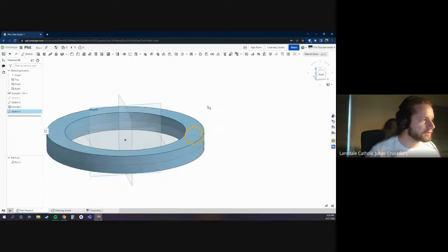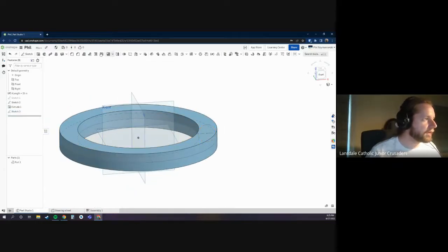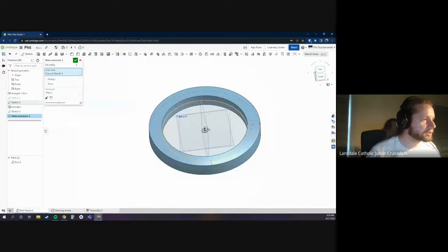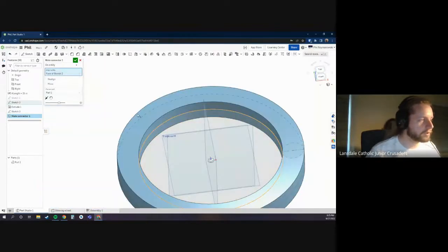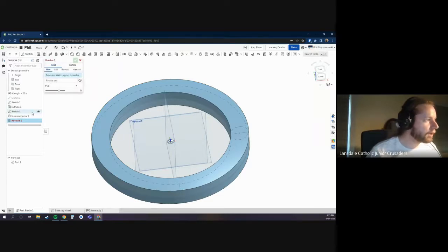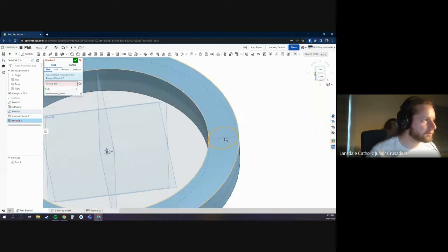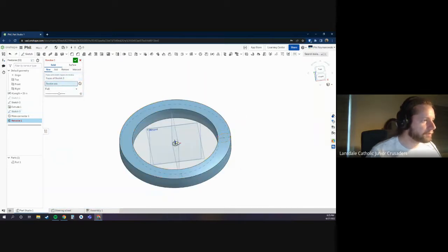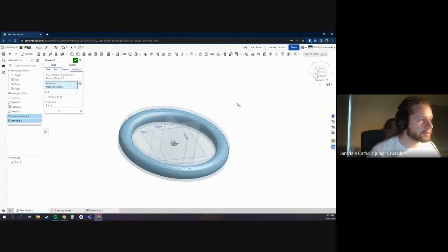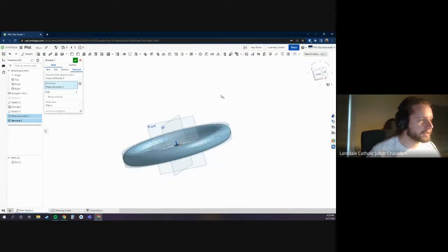And I'm going to use this sketch and do something called a make connector on the top, which is just a localized coordinate axes. It's just an X, Y, and Z. And I'm going to do a revolve of that sketch we just made, just that circle. It's going to be about that brand new make connector that we just made. And instead of add, it's going to be intersect. So it's only going to leave us with the material that is intersecting.